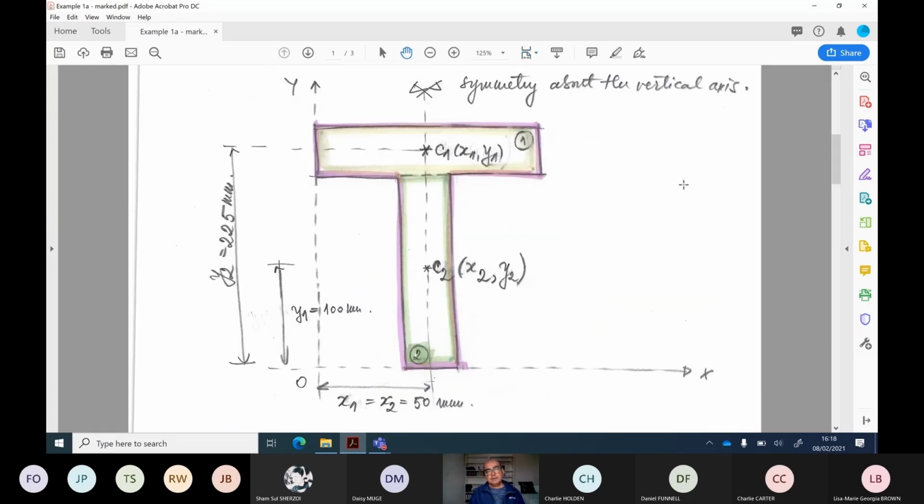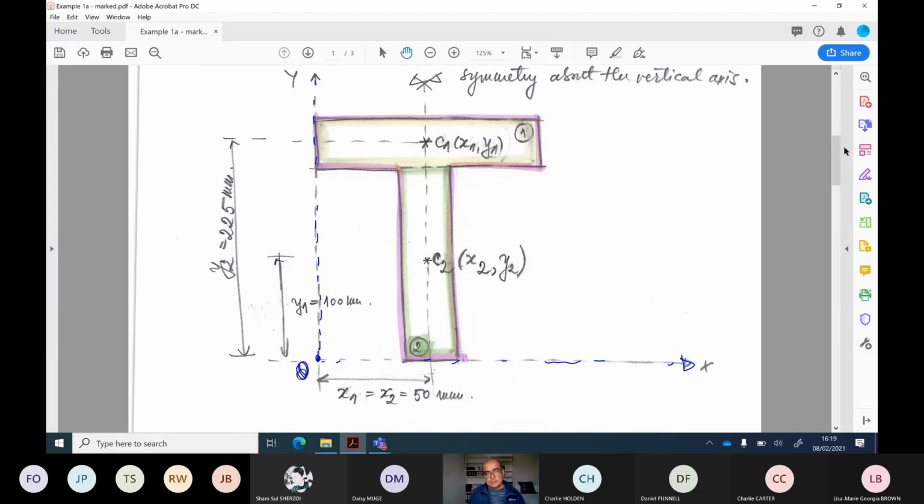The first thing is to draw the origin point, and then you have this x-axis. You can take this origin at any point, but I would prefer to take it at the extreme left point of the section. I would take the horizontal datum axis as the bottom point, and the vertical datum axis as the extreme left point. Wherever these two axes meet, I call it the origin. First, you have to locate the origin. In that way, you will be able to find out the centroid.